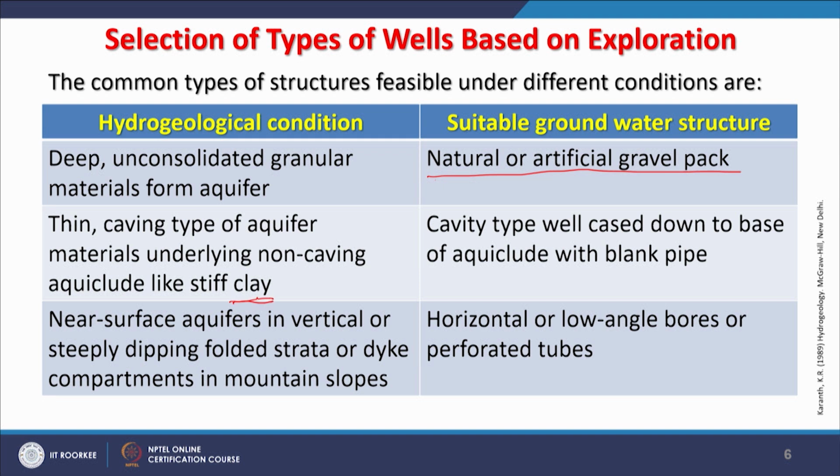Clay works as an aquiclude, as we know. So, in a cavity type well, it is cased down to the aquiclude with blank pipe. Only where the water can enter, only that part is left open, or through slits or screen. The rest is completely cased down to the base of the aquiclude, and in that way a structure can be